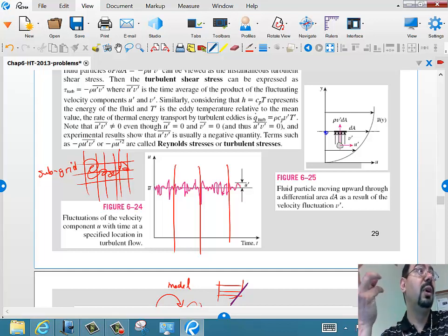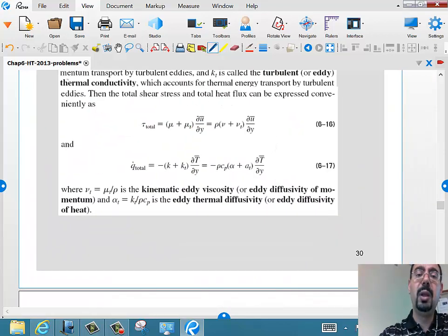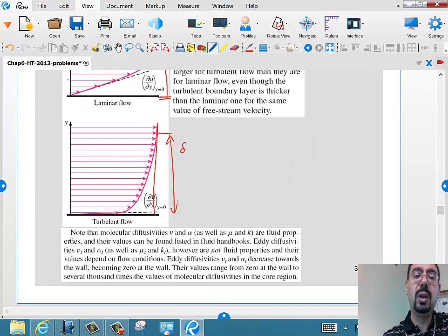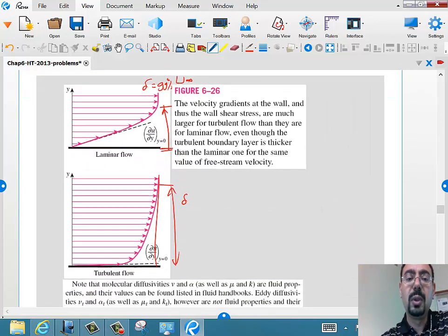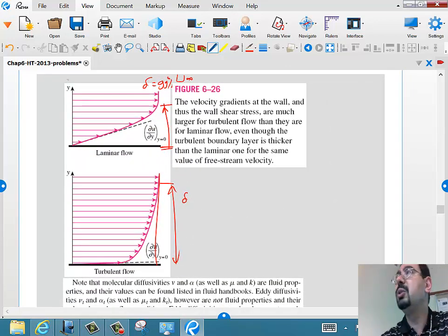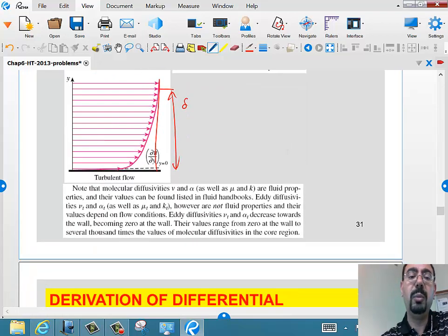And so if you give the engineer an explicit, empirical formula, so that he can immediately calculate the h, he will be very happy, rather than spending 5 hours trying to solve the velocity profile around the cylinder so that he can get the gradient, so that he can get the q leaving the wall. But there are ways to solve them, and let's leave this for a fluid mechanics course. And this is the boundary layer and how it's really different for laminar than turbulent.